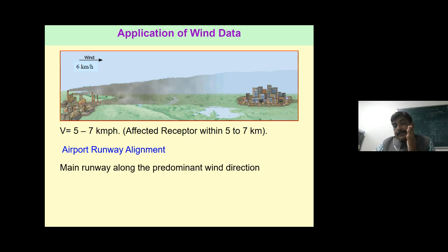If the wind is east-west and we set up a runway north-south, the crosswind will destabilize the plane and it will skid from the runway. Whenever the plane lands, care is taken that the predominant wind is either along with the plane or opposite to it. The aerodynamics can handle both, but not the crosswind.